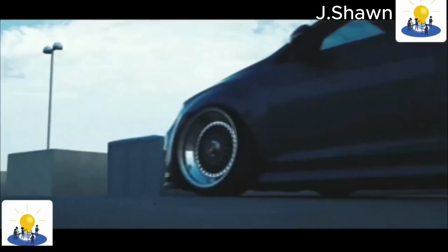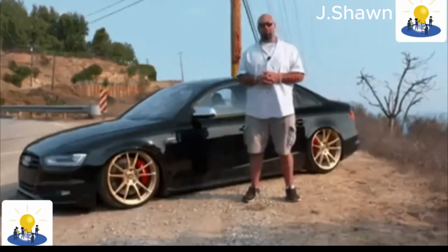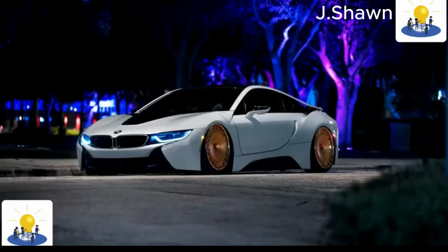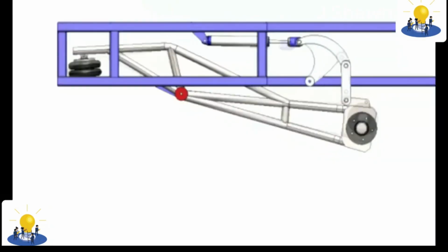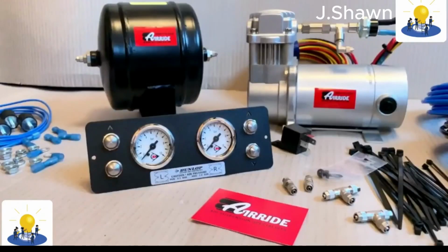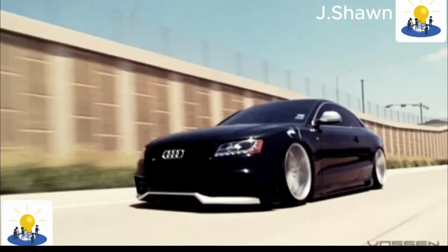Over the last decade or so, air suspension has become popular in the custom automobile culture. Street rods, trucks, cars, and even motorcycles may have air springs. They are used in these applications to provide an adjustable suspension, which allows vehicles to sit extremely low, yet be able to rise to a level high enough to maneuver over obstacles and inconsistencies on paved surfaces. These systems generally employ small, electric or engine-driven air compressors, which sometimes fill an onboard air receiver tank, which stores compressed air for use in the future without delay.